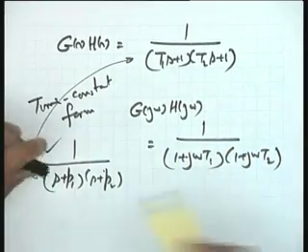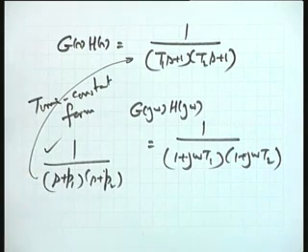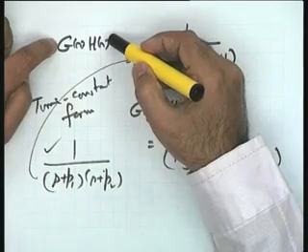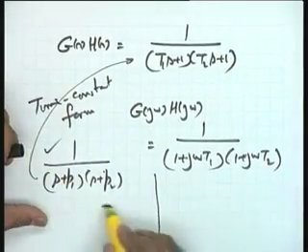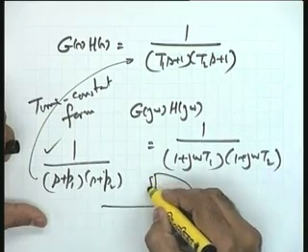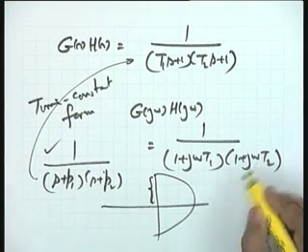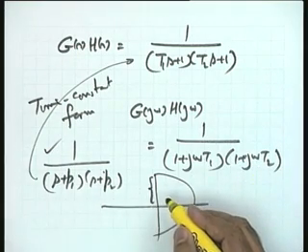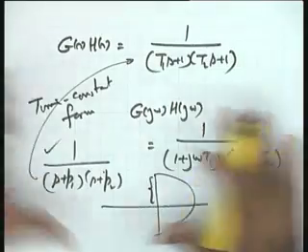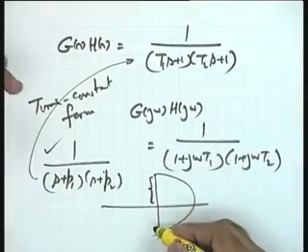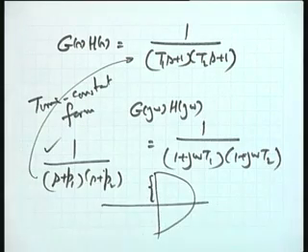These are the two complex quantities, and this is the sinusoidal transfer function. Why did I take the sinusoidal transfer function? Please note, I want to do the mapping of the entire Nyquist contour under the function G(s)H(s). We have already observed that this mapping effectively means the mapping of the positive half of the imaginary axis, because once the mapping of the positive half of the imaginary axis is done, the complete mapping is straightforward, the negative half being the mirror image and this being a constant point.